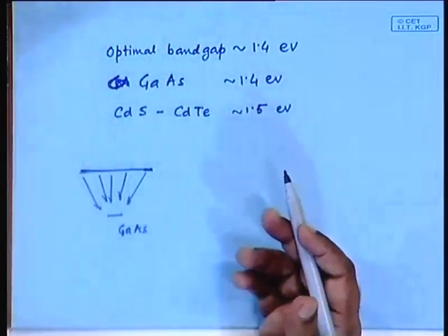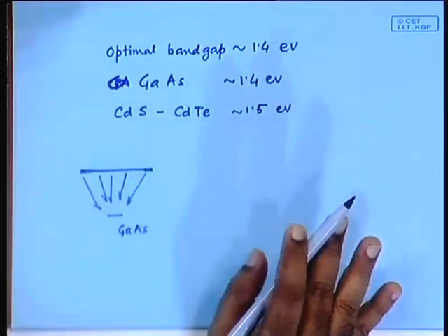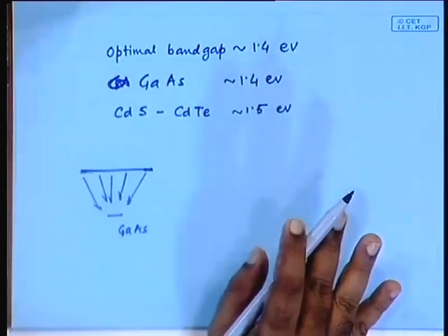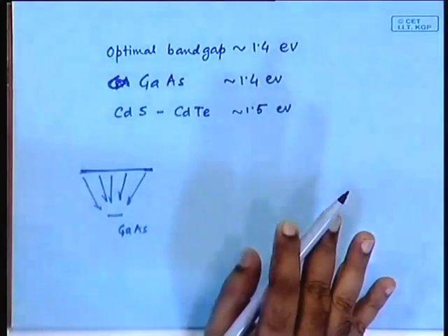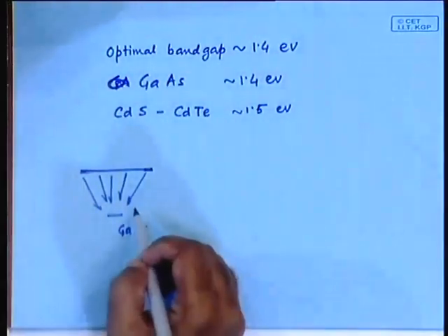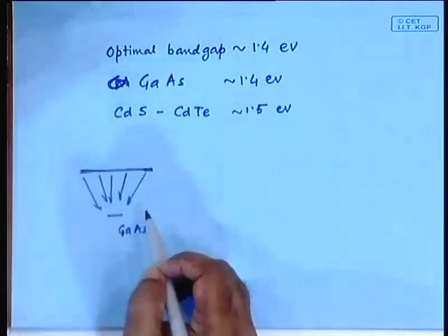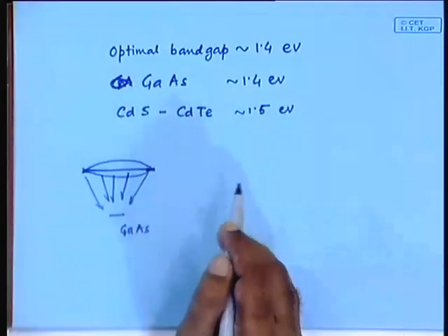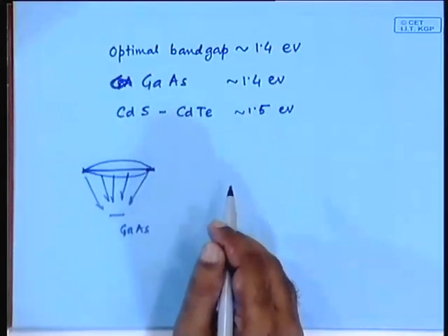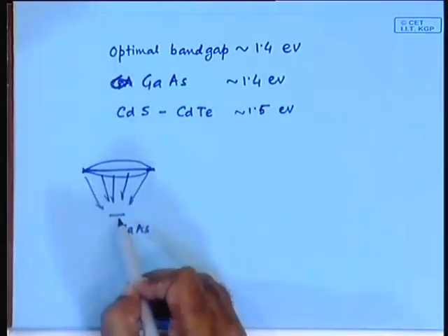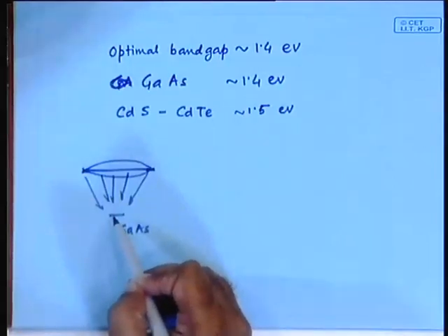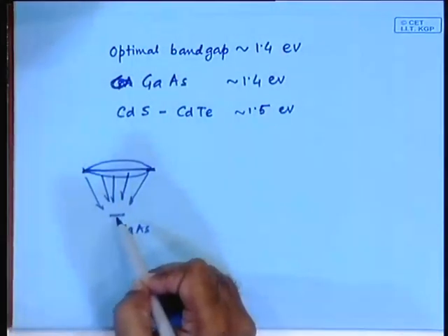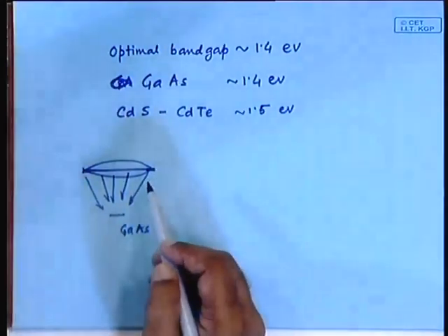What kind of concentrator can it be? Have you already learned concentrators? Yes, right. So, you have learnt that there are a few types of concentrators. One is the reflecting concentrator, the other is the refracting concentrator, and out of the refracting concentrators you have learnt that a whole big lens is of no use. We normally use Fresnel lenses. Yes, the Fresnel lenses are also considered in conjunction with gallium arsenide solar cells. So, very rarely will you find gallium arsenide solar cells considered as a standalone system; they are used in conjunction with some kind of concentrator.